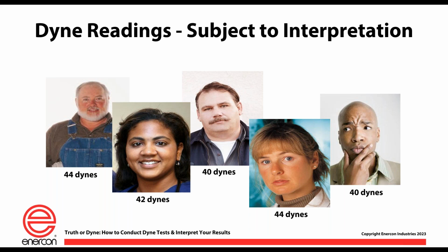So you really need to expand your horizon. And that's why early in the presentation, I mentioned to you guys, if you know what the surface energy of the liquid is, that can help you put into context what you actually need going forward. So you're not just throwing darts at the wall saying, well, I think this film needs 44, I think this film needs 50, I think it needs 38. There's no reason to do that. Go back to your supplier of the liquid and say, hey, how do you formulate this? What's the surface tension of the liquid? They should be able to give you some understanding of that.